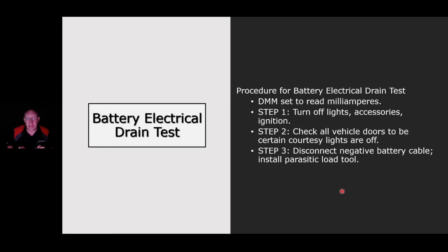So you need to be very careful and find some process, whether it be putting a rubber cone right in the door jamb or something that won't allow that door to close and allow that latch to hit its latching point on the B pillar of the car. Because if it does, you could bend the B pillar, you could damage the latch in the door. It just becomes problem after problem for you. So you've got to find a way, if you're going to do that, to make sure you and or somebody else that doesn't know you did that doesn't come by and try to slam that door and damage the vehicle. But you need to make sure all the lights are off inside, make sure that everything's out.